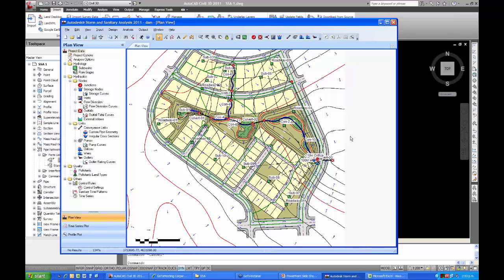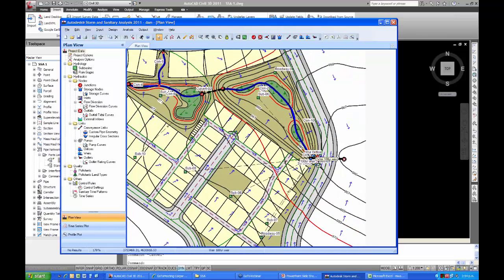Okay, they've gone through and made a whole subdivision here of this area. What I'm interested in is down on the right hand side here in the middle. There's a large detention pond that they've created. There you go, you should all be seeing that now. So here's the detention pond over here on the right. They have a bunch of junction structures and pipes in between those. Some of those are open channel pipes, or just specified as open channel, so we get the correct flow characteristics in there. I'm going to zoom in on the outlet structure because that's what I wanted to look at here.